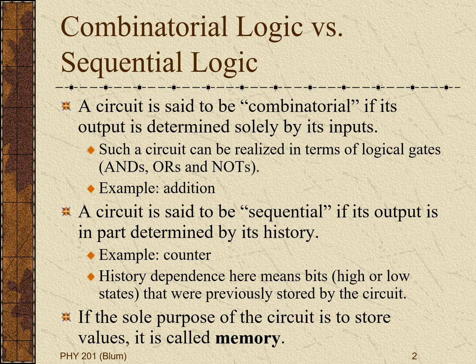A circuit is said to be sequential if it depends in some way on its history. An example of this would be a counter. The input to a counter will be telling it to increment, but what it will increment to depends on what it was previously. So it depends on its state. If the counter was 34 and you tell it to increment, it will become 35, and so on. So it depends on its history, or on its state, and we need to know its current state and not just the inputs.